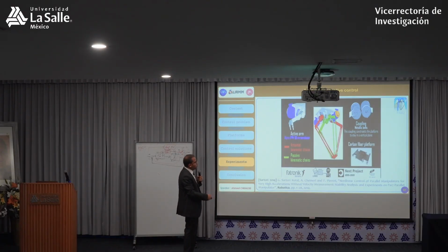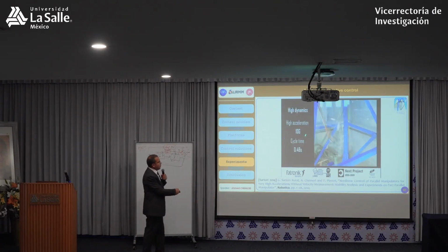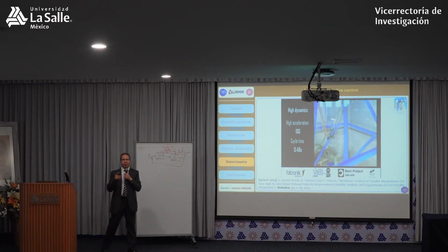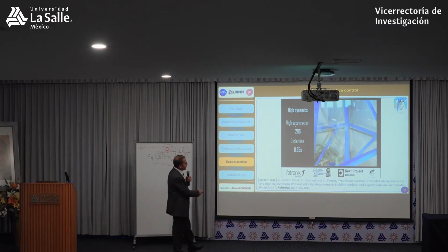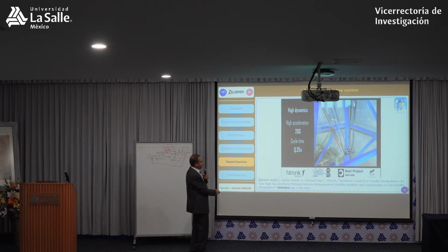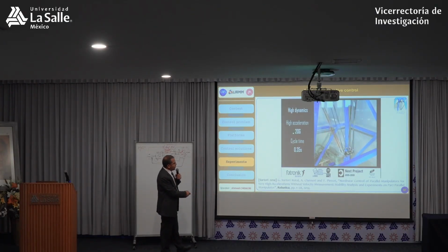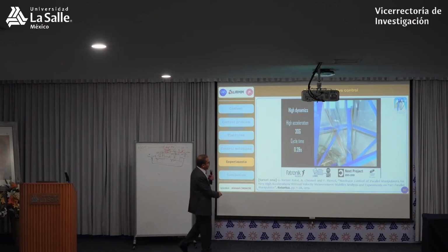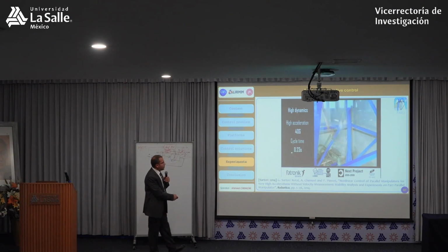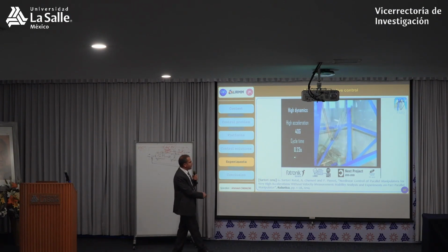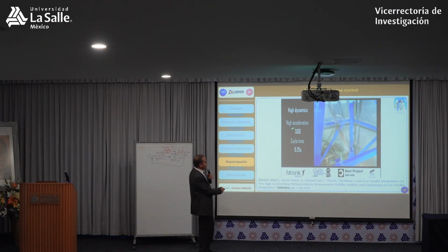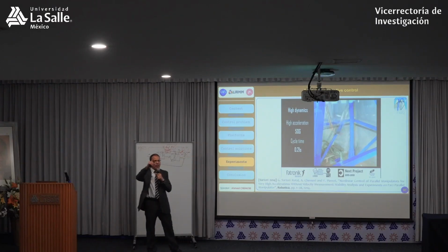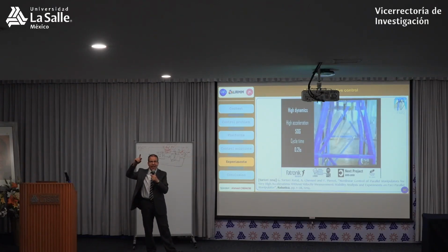So I will show you some results. 10 g of maximum acceleration, cycle time 0.48. 20 g, 0.35. 30 g, 0.28 seconds cycle time. 40 g, 0.23 seconds cycle time. And the maximum, 50 g, 0.21 seconds cycle time.